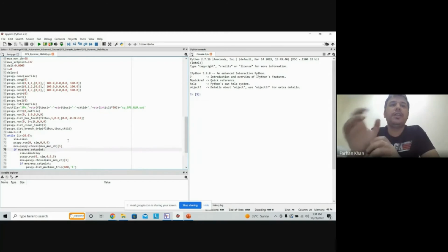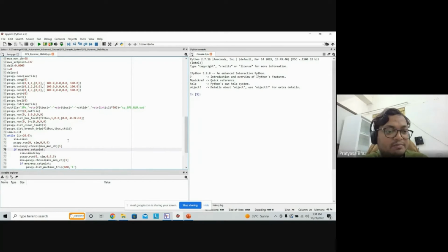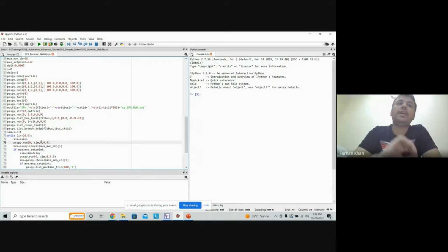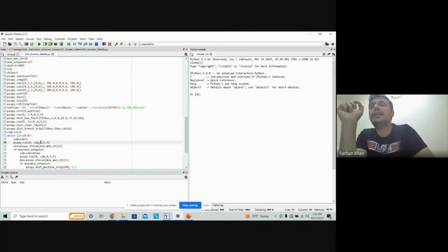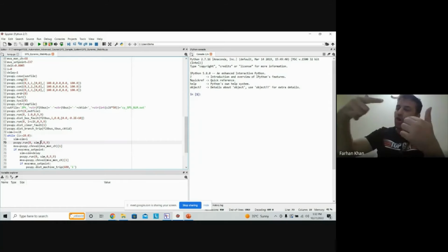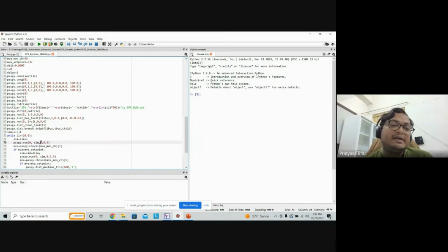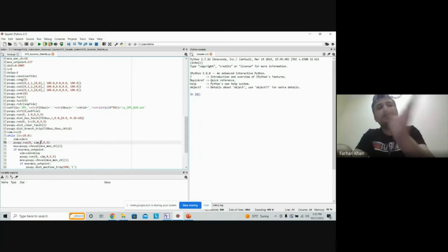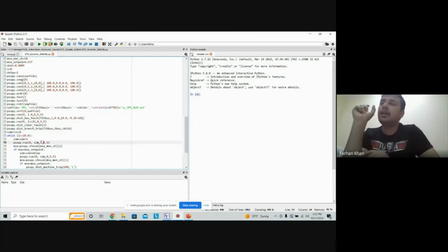So moving on. Now I am checking psspy.run(0, sim, 99, 9, 0). What does it mean? This zero is print at every time step, zero time step. So in my simulation, nothing is going to be printed onto your console after I am running. And these nine, and 99. So t is equal to zero. Then write every, so I am writing after every nine steps.